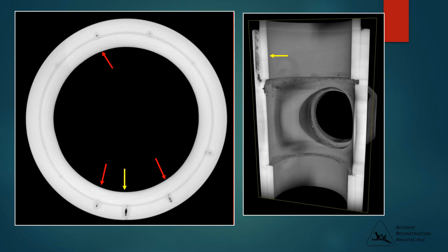But you can also see these axial radial features in this image marked with arrows that show voids in the T hub. And then another axial slice shown at the right. Basically, the yellow arrow is centered on the same area shown in the yellow arrow on the left image. And you can see the apparent porosity in that connection. The other interesting thing to point out here is the difference in wall thickness of the hub on the right and on the left.